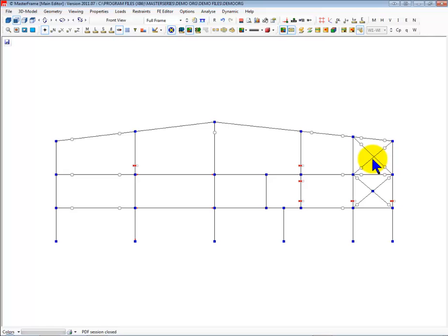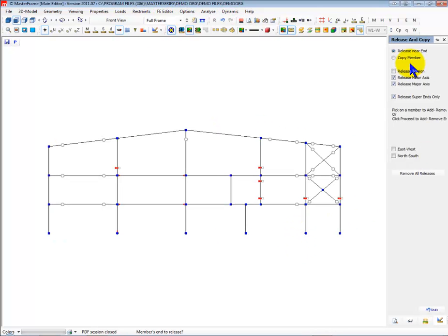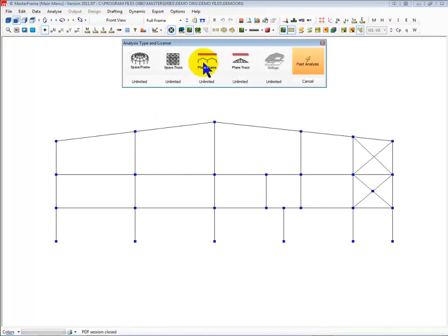When we put a release at both ends of a member that is fully released, then it will actually put a torsional restraint on one end to stabilize the member. But because this sees this as two separate members, it doesn't do that in this case. So I would actually need to go into two of these and take out the torsional release. So that is restraints, end release, member end releases, and leaving the torsion in, I would just come along and put those two back in, and hopefully that will get me my...